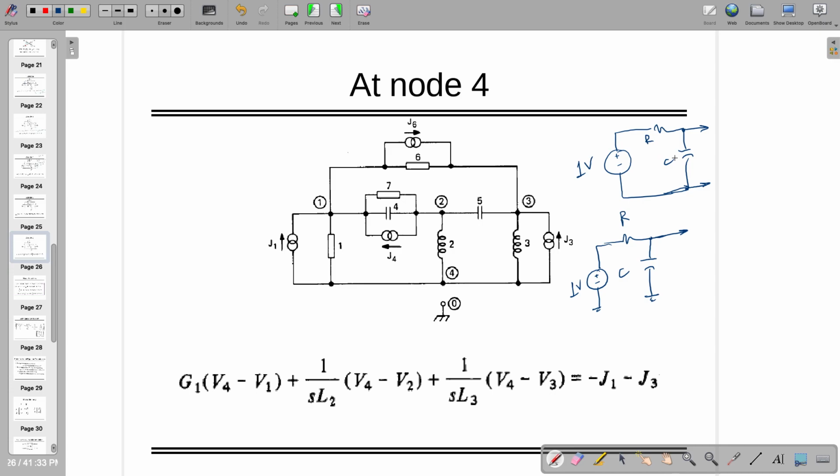We see voltage difference, not voltage value at any node. Right now it's V4 with respect to ground. Ground is a different value. If you take it equal to 0, then the answer will be the same, for current, I'm talking about current, not voltage. Right now, look, I have not kept V4 anywhere at 0. In between V4 and this node and this node, there might be something else which I am not showing right now.